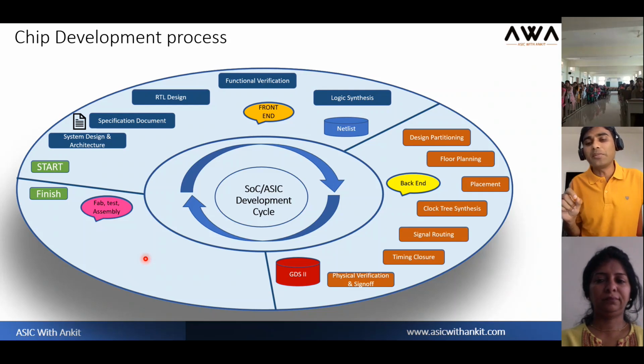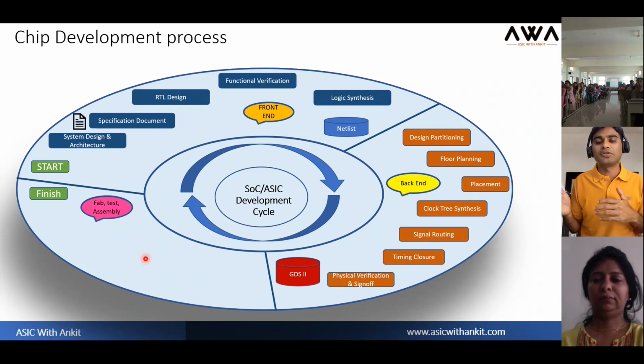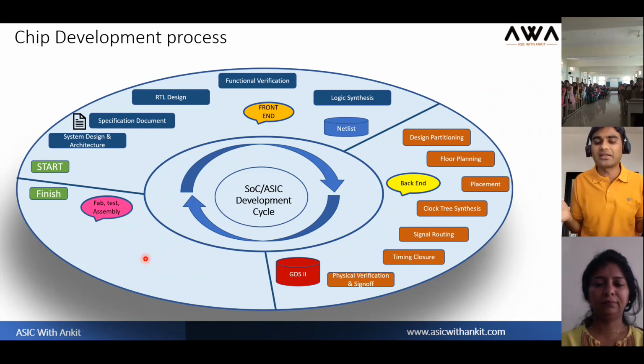As you may remember, there are a lot of different technologies like 65 nanometer, 10 nanometer, 7 nanometer, 5 nanometer, something like that, right? Let's say we have planned to go with 7 nanometer for whatever reason, then we need to tell the foundry to give us the 7 nanometer related constraints, timing closure and all of those relevant parameters.